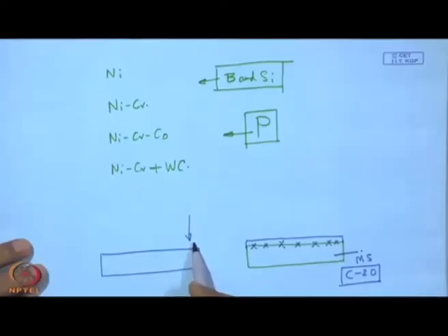So, it is not at all a protective atmosphere, and when we use this oxyfuel torch, though it is a neutral flame, the oxygen present in that zone environment can cause oxidation of this material. But this should not be a big problem for us, because then comes the second very important role of boron and silicon.